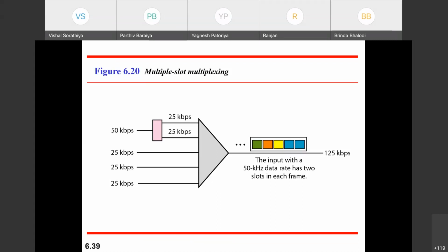Say the answer to that. Which digital component will divide a frequency by 2? It is a D flip-flop. Whenever you give the clock to the D flip-flop, and the same input you give to the input D. D में होता है ना, D होता है, clock होता है, Q bar. These are the structure.